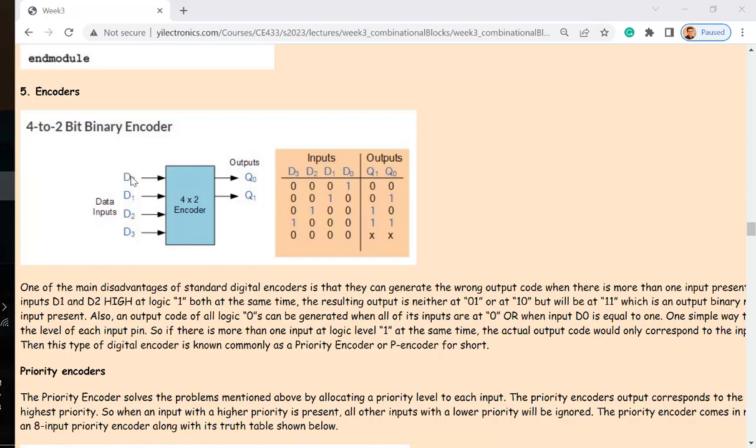It's just a truth table. Then after the truth table, write down all these logic equations and simplify them. Use a K-map to simplify, or just type it directly in Verilog, because the computer can handle everything for you. You don't have to do it manually. And you're done. You can design the circuit on the FPGA.